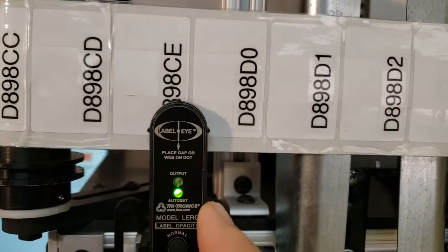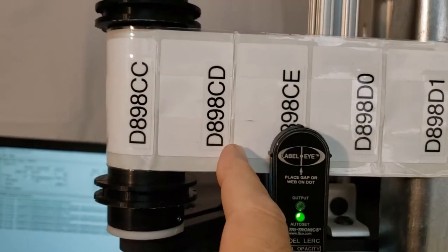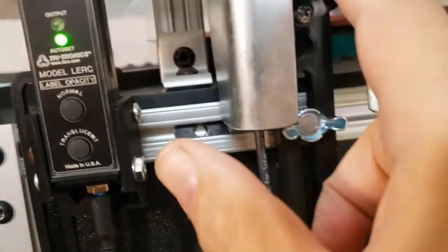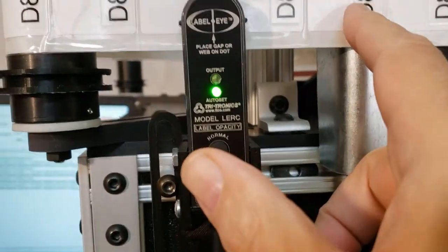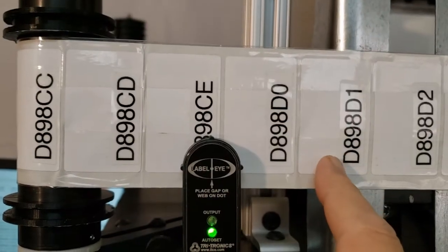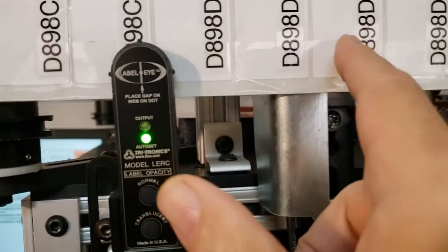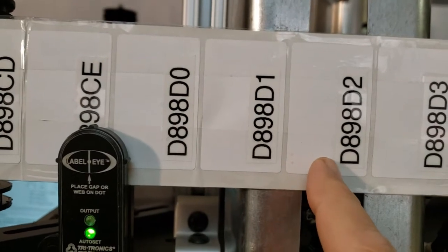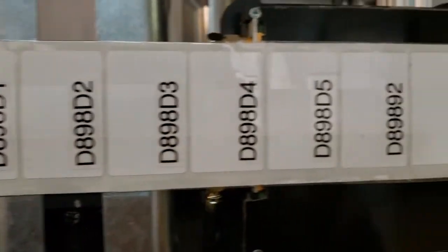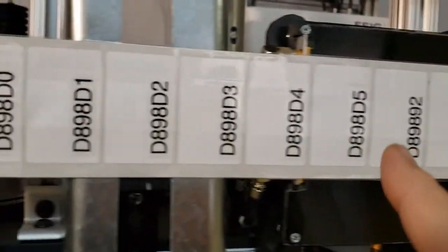When the gap sensor fires, as it will when this gap goes through the sensor, the system will read a tag here, and it should read this D8 98D1 at that time. So to read that, figure out what encoder it's supposed to go to, and then schedule that encode operation for one of the 3 downstream antennas.